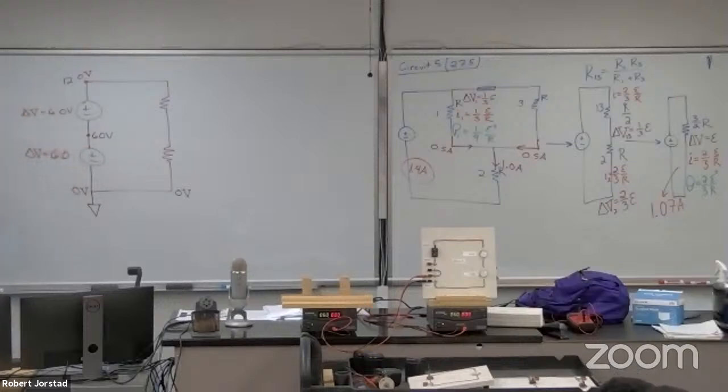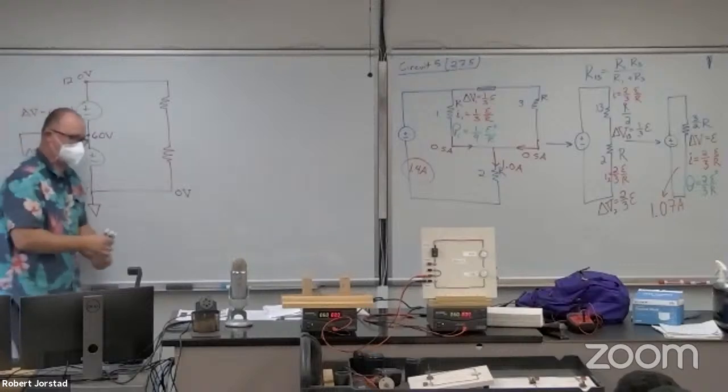If I stick another one on there, where we're going to run into trouble is this is also connected to ground. But that means it's also connected down here. How much resistance do you see? Some or none? How about almost none, right? There's the wire itself. You're going to have 6 volts across here with almost no resistance. Not good. We do not want that connected to ground on the other one.